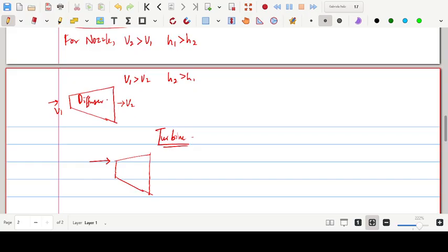So this is process 1 and 2, inlet and outlet. These are the blade. The blade is what will be rotated. You understand now? So considering the same formula that we used the other time, we have Q equals m dot, then we have H2 minus H1. This formula is not new to us again. Plus Z2 G minus Z1 G plus the kinetic energy. I can put 2 outside here. So here now is plus work done. There will be work done.